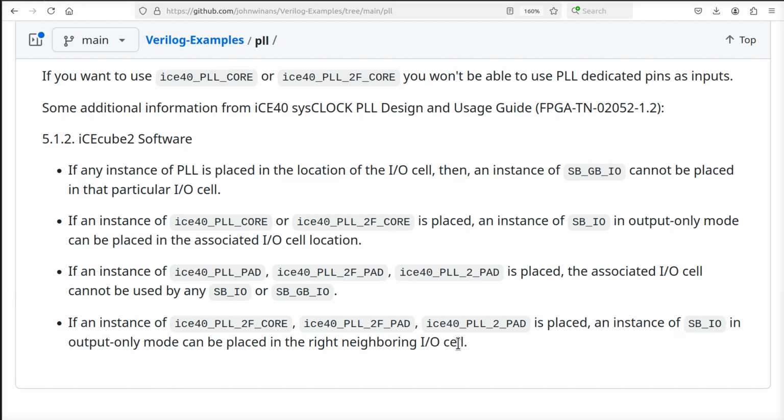And it may have to do with the fact that the pins are usually paired together on an FPGA on some of the I/O banks so that you can gang them together and use them in a DDR type configuration. And that, I'm just theorizing here, okay? Why in the world would there be this relationship? Well, it turns out there oftentimes is, and there could be some circuitry that the PLL prevents you from using.